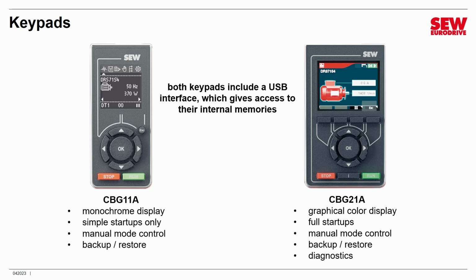Now, why would you want to do that? Well, it's simple. If you've run a backup, you could then plug a cable in, hook it to your PC. It will behave kind of like a giant memory stick, and you can download that backup and archive it somewhere as a file on a PC. And that is really a smart thing to do, keeping an archive of a VFD setup.